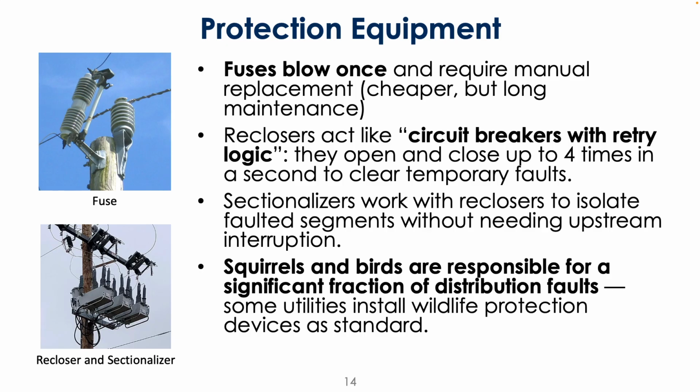So this stuff helps prevent that, right? And so the fuse is kind of the simple version of that, where yes, someone will still need to come out, but at least it's faster and less costly than replacing a transformer. And then with the recloser, hopefully you can automate some of that away. And just to reconfirm, the sectionalizer helps detect if there's a fault and then informs the recloser on what to do.